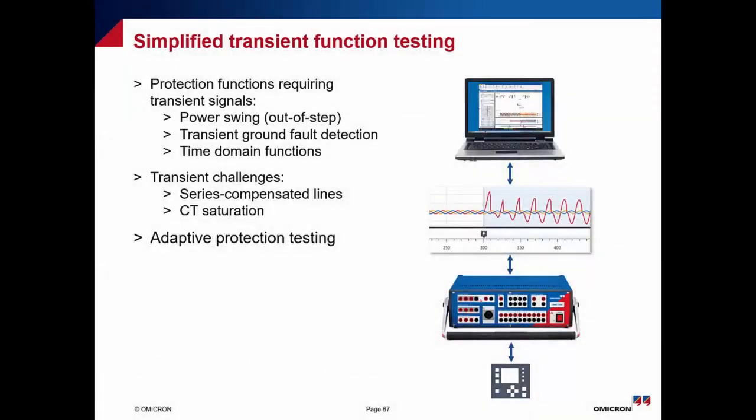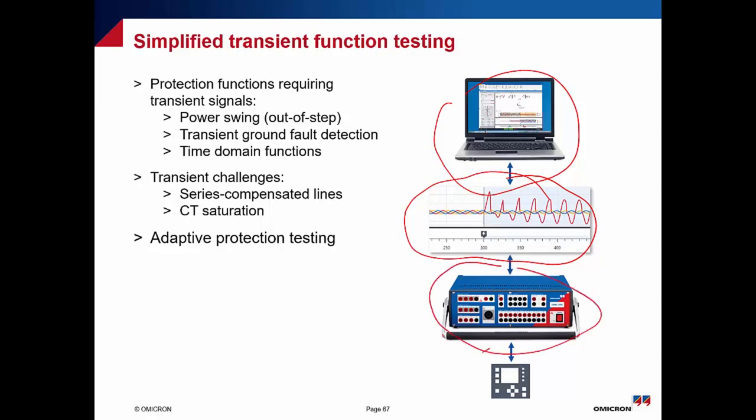Very easy approach. We can summarize that we need a PC with software, with a license, to start drawing the topology of your protection system. Then it will automatically calculate and show the sine wave of the expected, more realistic calculated signal, which should be injected by the CMC into the relay to get the feedback. That can be done very easily by using Relay Test with the CMC directly.